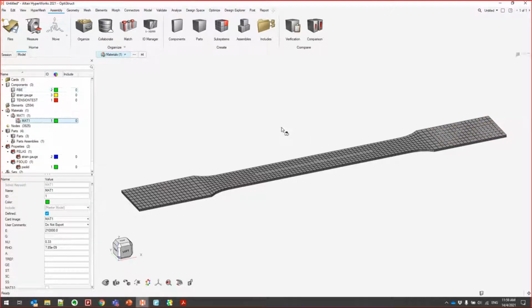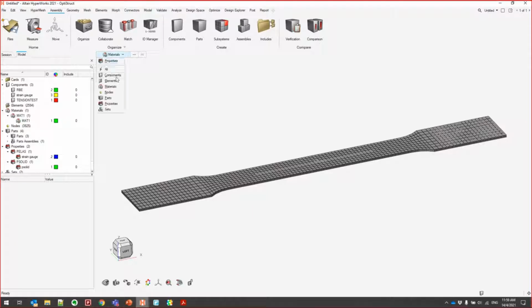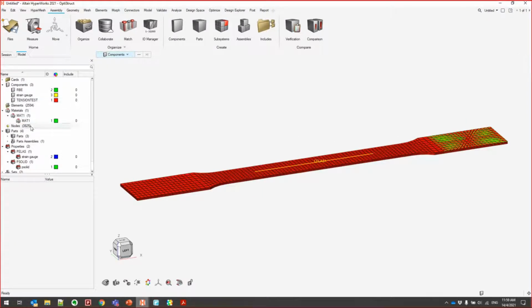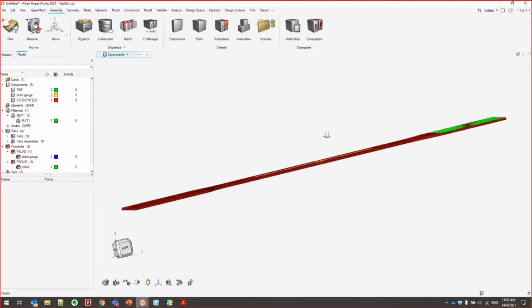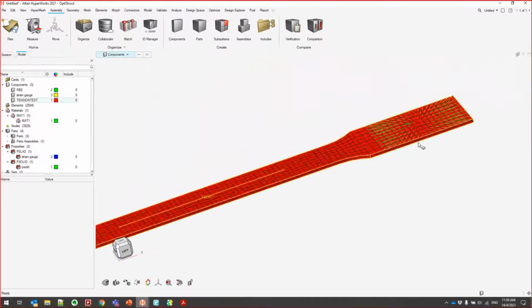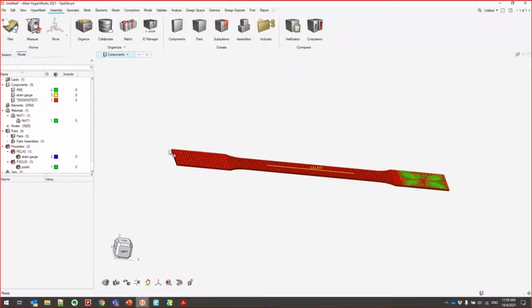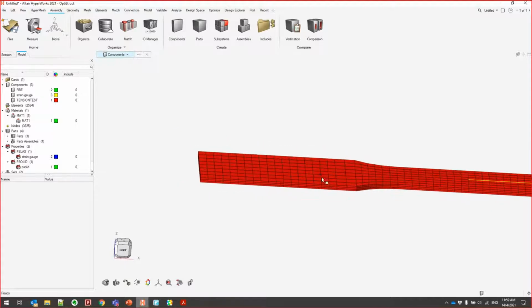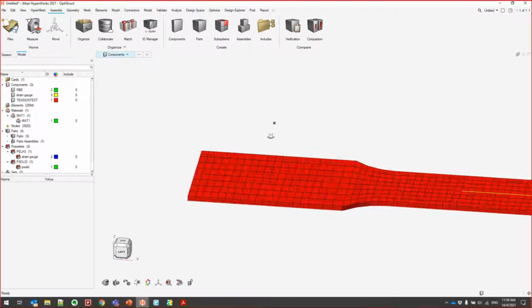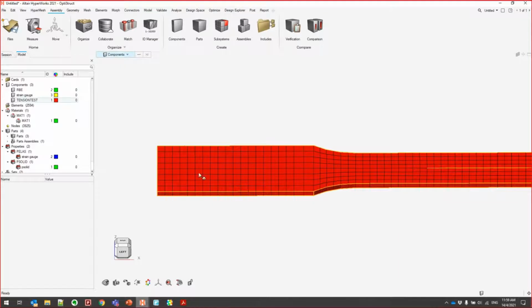Okay, I have my widgets already. Right, so this is where I'm going to pull it. The other side is where I'm going to clamp it. Let me just clamp this part first. When I clamp this, I'm not going to clamp the entire thing. Let me hide some of these elements first.